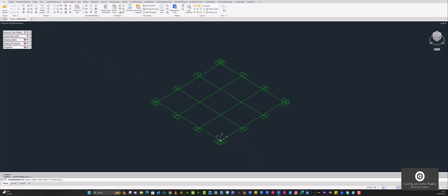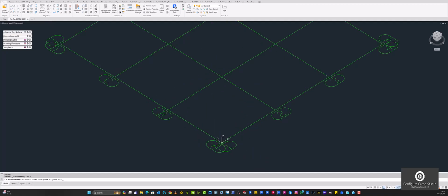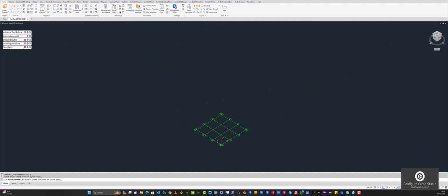Okay, all right, select that, go to our first point, which is A and 1 insertion point. Then we insert our height. Our height is 8310, which is the eaves height from our drawing. Then we hit enter. All right, the command is not yet completed. So if you want to exit the command, you have to hit enter twice.